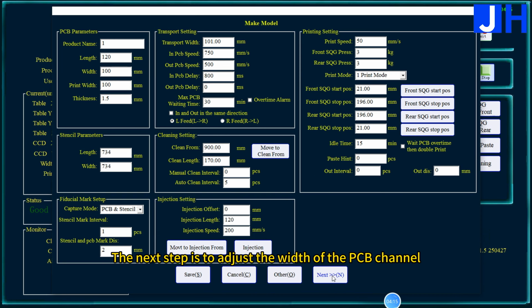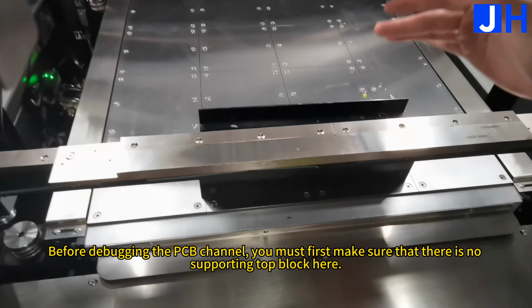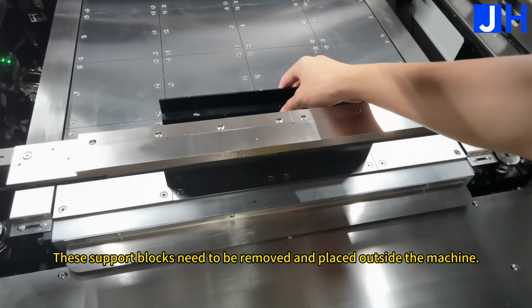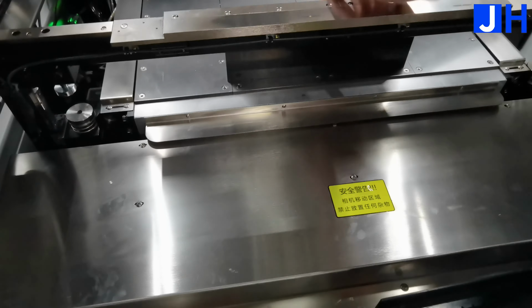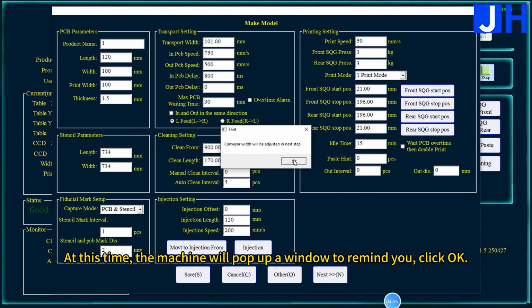The next step is to adjust the width of the PCB channel. Before debugging the PCB channel, you must first make sure that there is no supporting top block here. These support blocks need to be removed and placed outside the machine. Then, we can adjust the width of the PCB channel. Click Next. At this time, the machine will pop up a window to remind you, click OK.